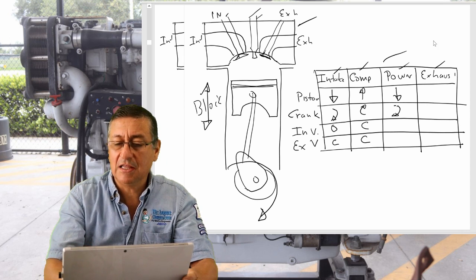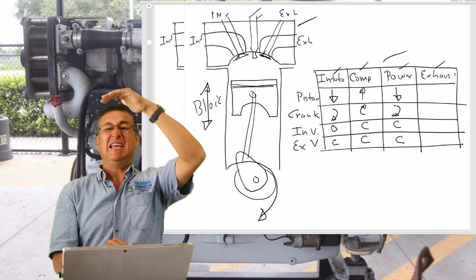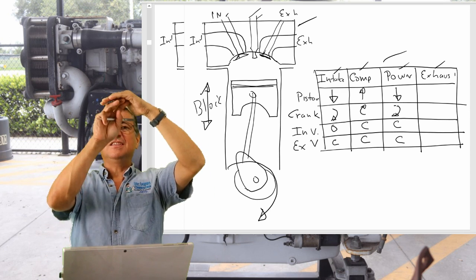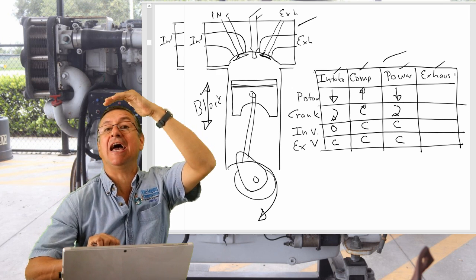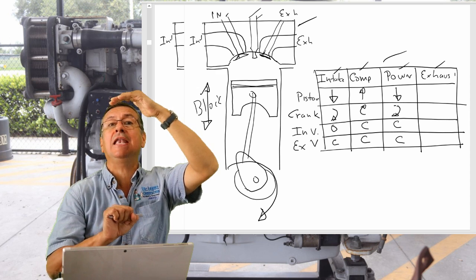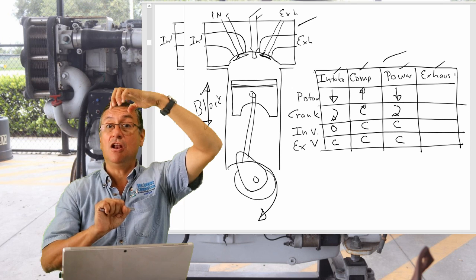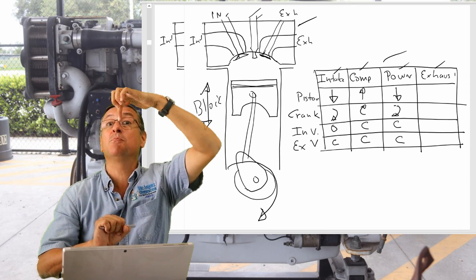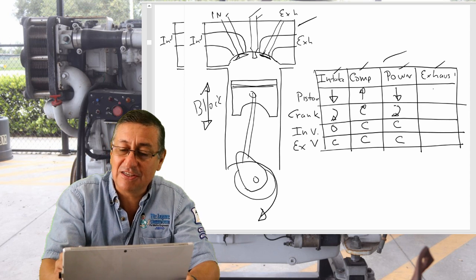And the valves close. Now the piston is at the bottom again, and all of this cylinder is full of smoke. Right now the piston tries to go up again, and what happens with the valves? Intake stays closed and exhaust opens, and the smoke goes out. This is exhaust. The piston is going up. The crankshaft rotates another 180 degrees.